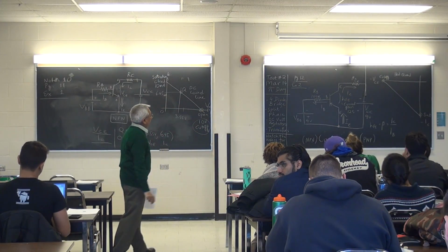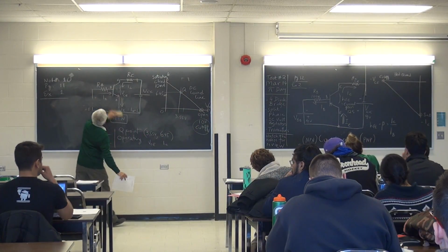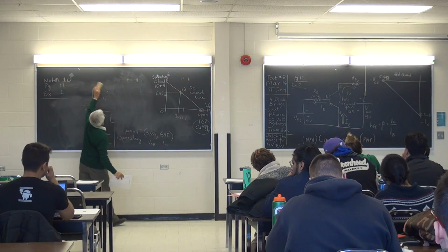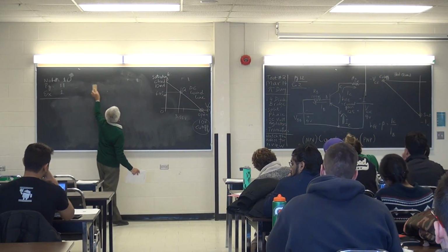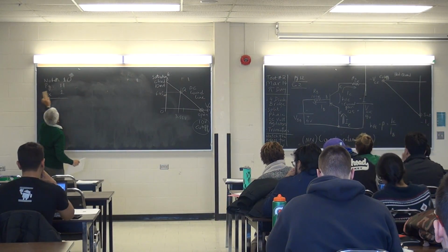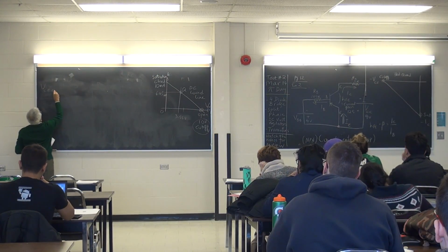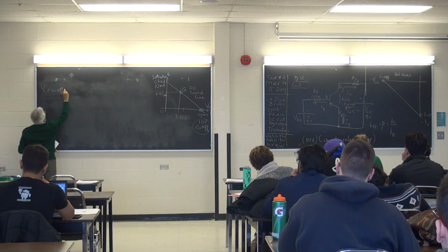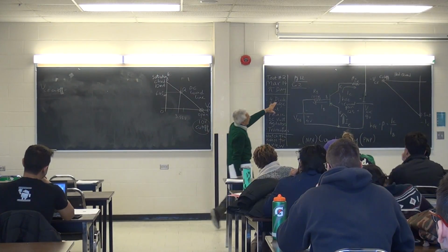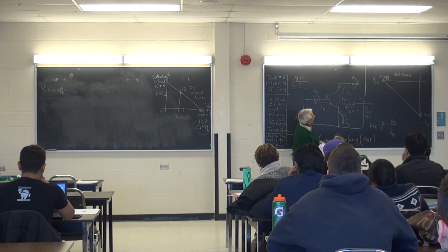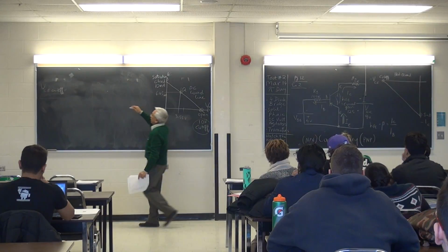And let me calculate cutoff. Okay, here we go. First calculation. VCE cutoff is saying that the transistor is open. So if I was to replace this transistor with an open switch like this, okay, so let's show an open switch. So like this.